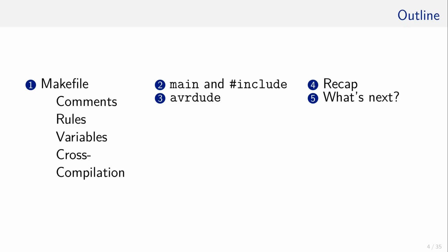Before ditching the Arduino IDE, there is something that we need to address first. Currently, even the simple blink program consists of two functions, setup and loop. However, according to the C standard, every executable binary needs to have a function called main, which serves as an entry point to start the execution. Libraries are exempted from that rule, and hence they cannot be executed directly. Their functions can be called by another program which is executed and therefore has a main function. So the question is, where is the main? That question will be answered in this session as well.